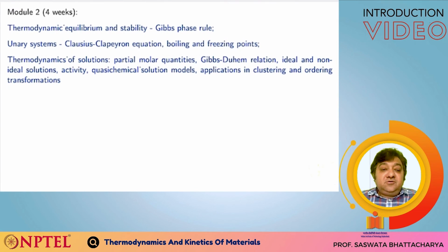Then in module 2, I will look at the governing principle for thermodynamic equilibrium, and this is the principle. This Gibbs phase rule is the principle, and it is used to construct phase diagrams to understand the equilibrium maps of phases, and I'll also talk about stability, like stable, metastable, and unstable equilibrium.